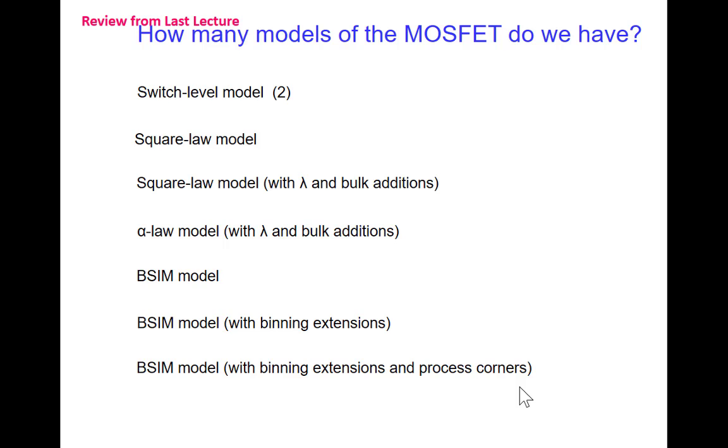characterize the device. But that's not good enough, because sometimes we design a device and fabricate it. We see the threshold voltage a little bit low. If they're a little bit low, transistors are a little bit faster. Or if the threshold is a little bit higher, we want the output a little bit slower. So we have corner models. Oftentimes either 4 or maybe 16 corner models. And each of those corner models corresponds to each bin, corresponds to that 95 parameter transistor model. So at the end of the day, what we have is a model that has several thousand parameters in it. And we still don't have the device well modeled.